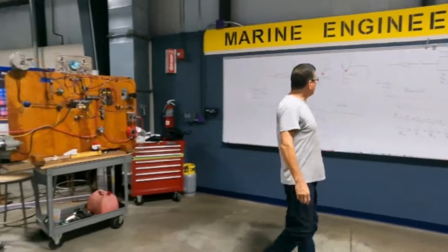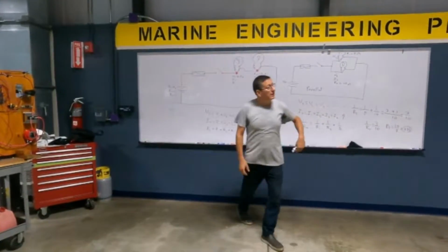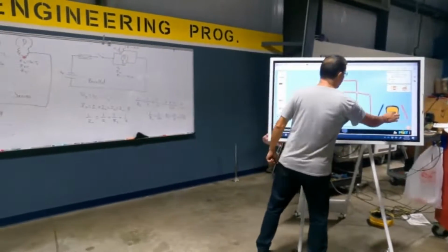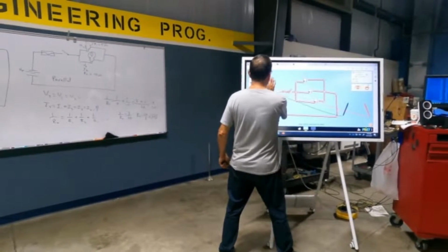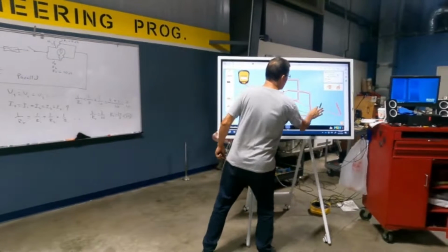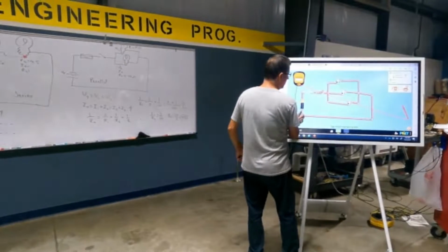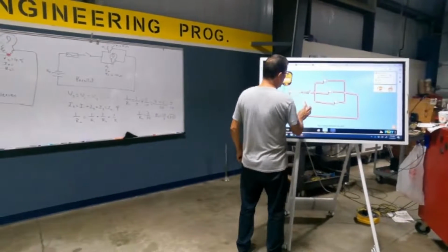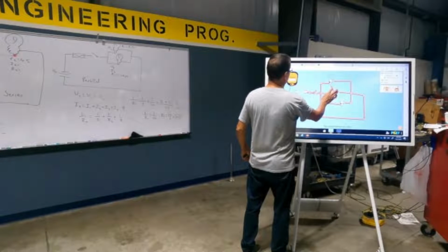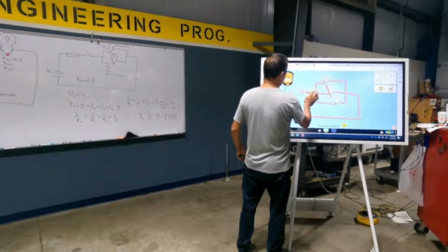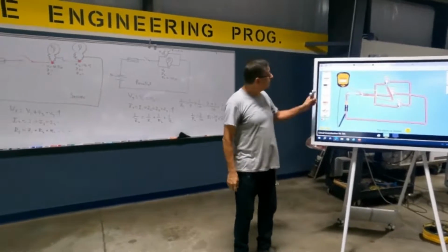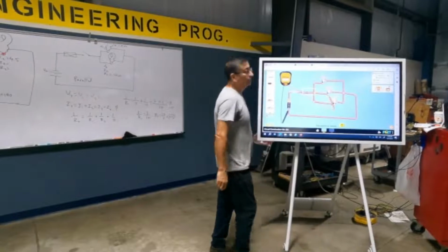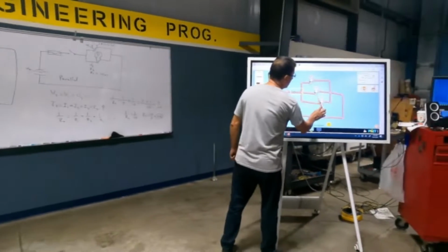Let me verify, for example, that it is true that the voltage is constant. We are going to use the voltmeter. Let me put the voltmeter here. Okay, I put this one here. And we are going to check the voltage in the first one here. Of course, I need to close. It's 9 volts, 8.96, no? What about the voltage in the second one? What about the voltage in the third one?